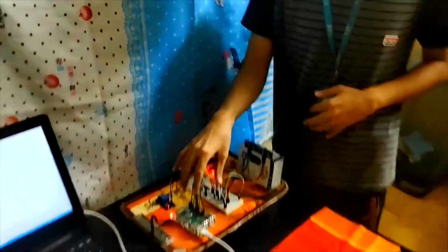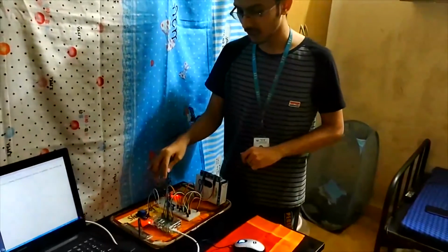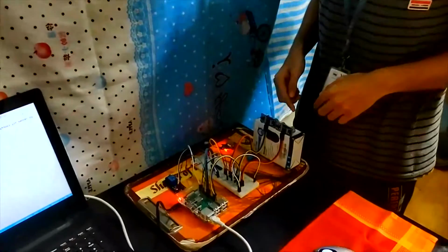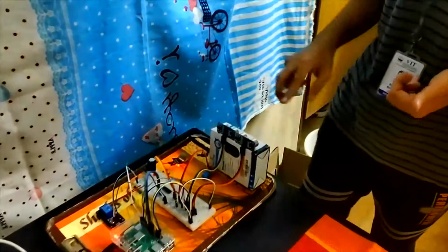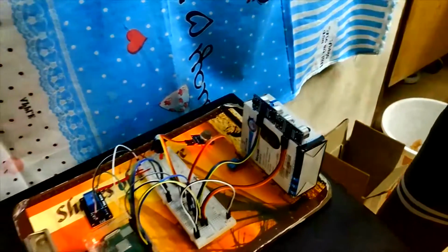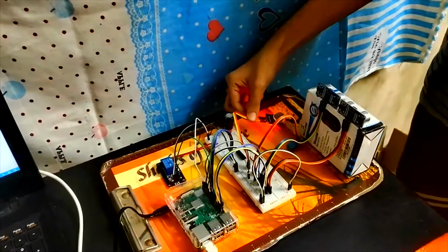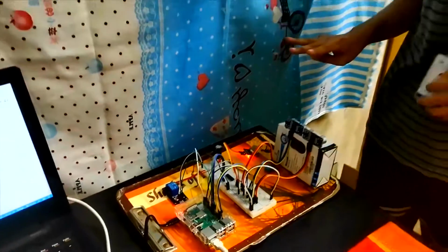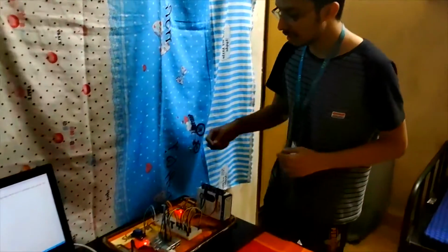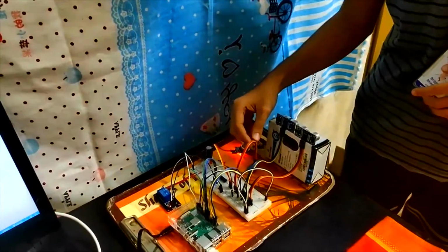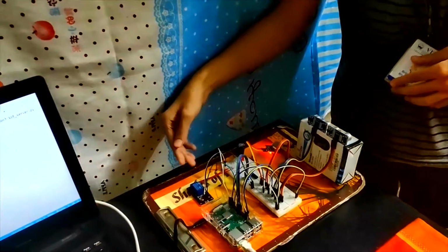The Raspberry Pi is the governing component of our project, which controls the hardware like the sensors. The sensors included here are two ultrasonic sensors, one for the control of the geyser, one for the control of water tanks, and one MQ2 gas sensor that gives us simultaneous readings of three different parameters: the smoke levels, the CO levels, and the LPG levels. Other than that, we have a DHT11 sensor which gives us the values of temperature and humidity, and we have here a relay module.